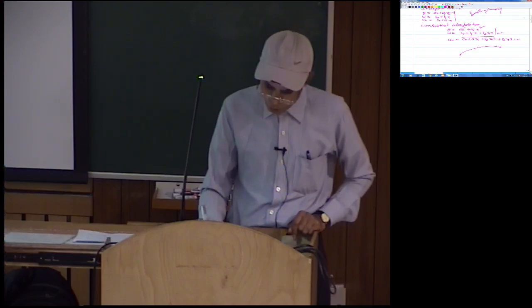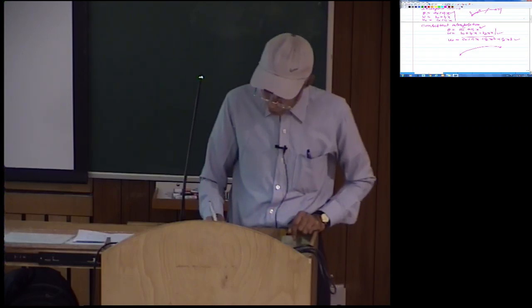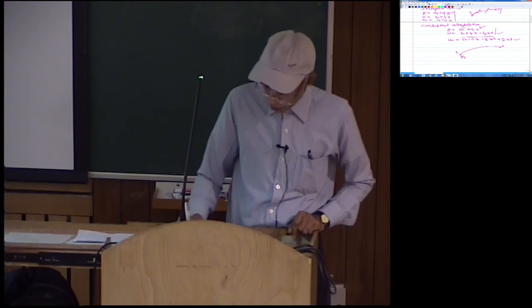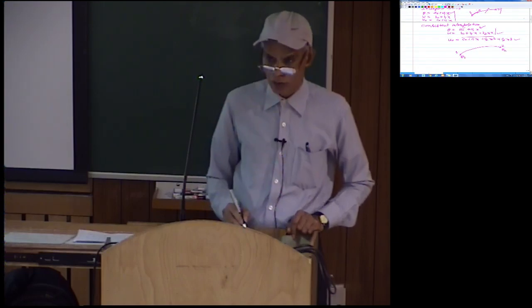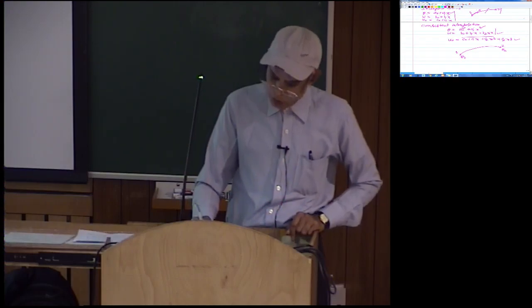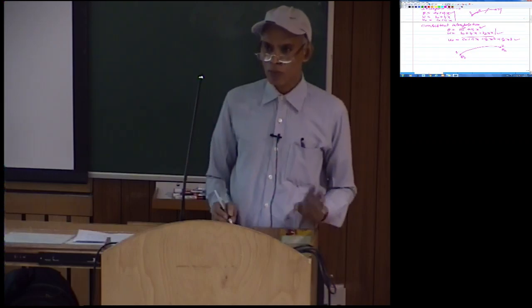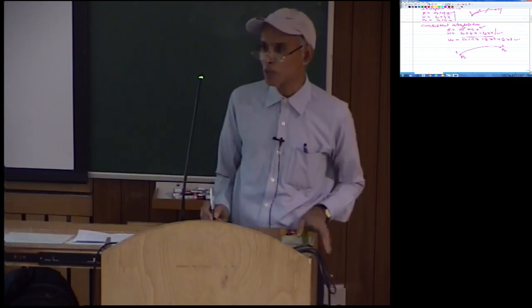So theta has got two unknown constants. So we can have theta as the degrees of freedom at these two end nodes. This is node 1 and this is node 2. Theta 1 is one degree of freedom here, theta 2 is another degree of freedom here. These two degrees of freedom can be used to represent a0 and a1. Then w has got 3 constants. Three constants means there must be 3 degrees of freedom corresponding to w.